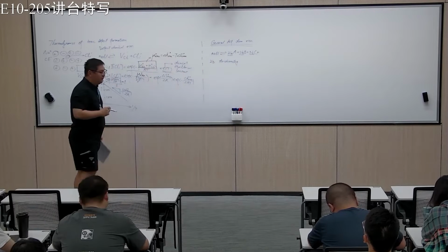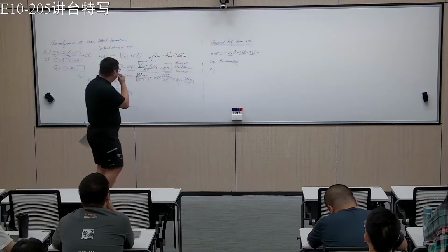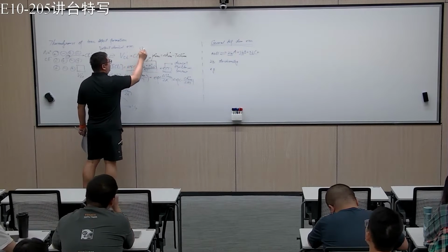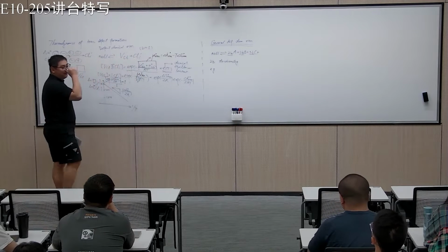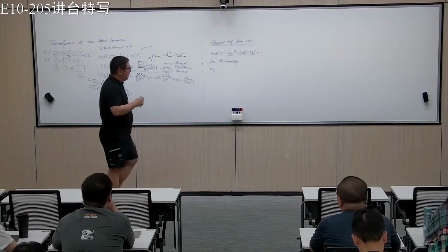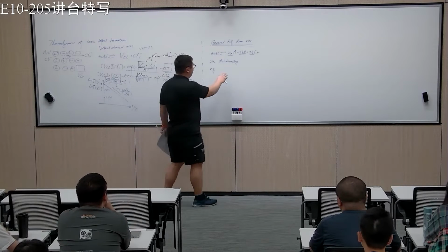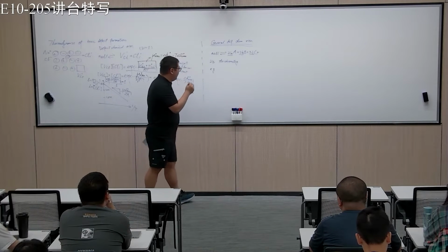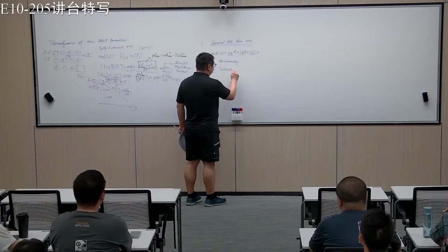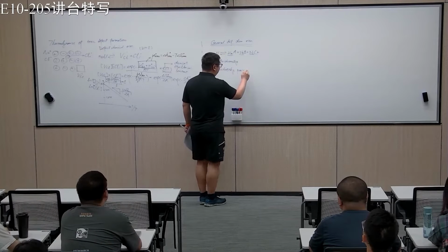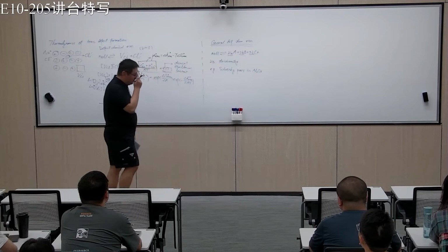So what does that mean? For example, of course here the mu is basically 1. You can imagine there's 1 here, there's 1 here, right? Of course if you go to more complicated cases, then you do have different stoichiometry. For example, think about the Schottky pairs in alumina, aluminum oxide.